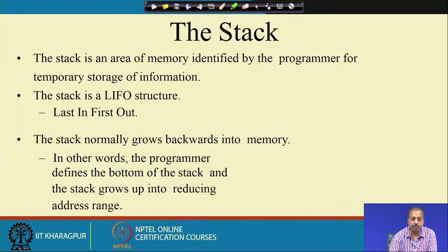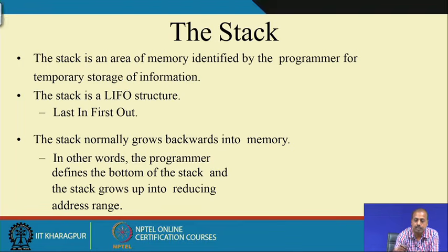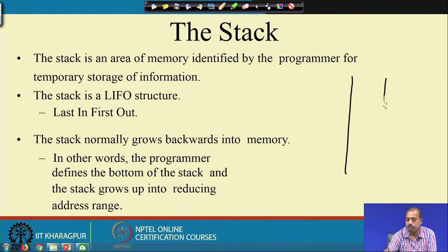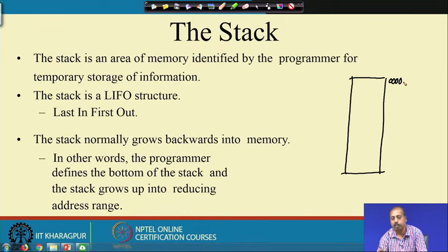Stack normally grows backwards into the memory. What we mean is like this. If this is the full memory, with addresses from 0000 to FFFF if I have a 16-bit address bus, that is a total of 64K space. Out of that, my stack will start at this location, say 8000.